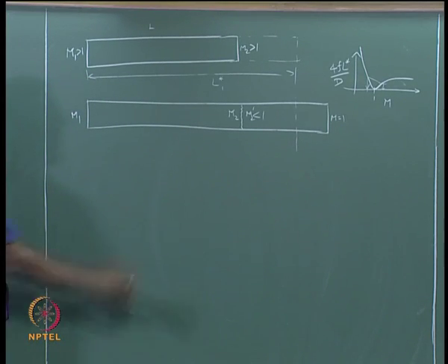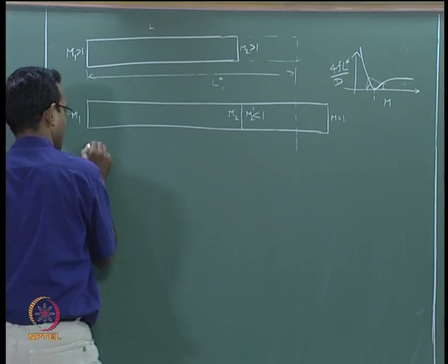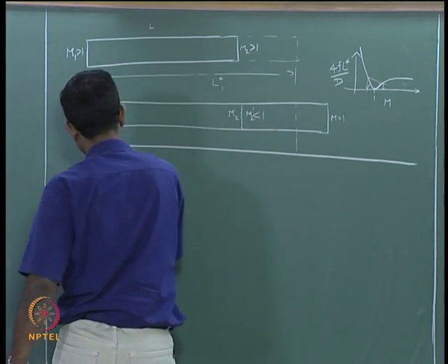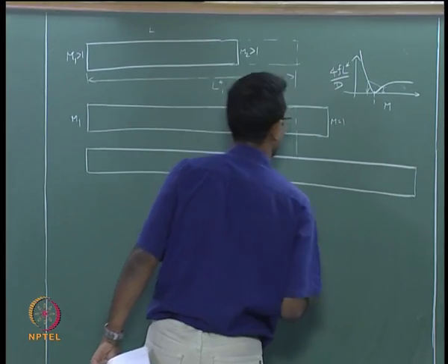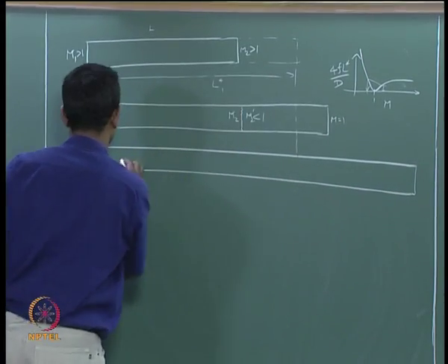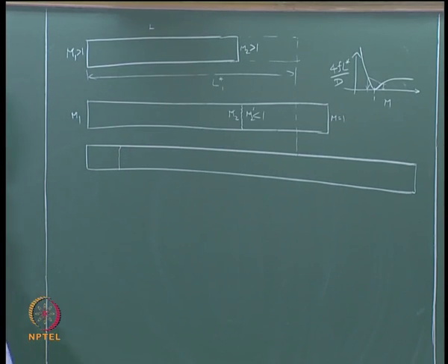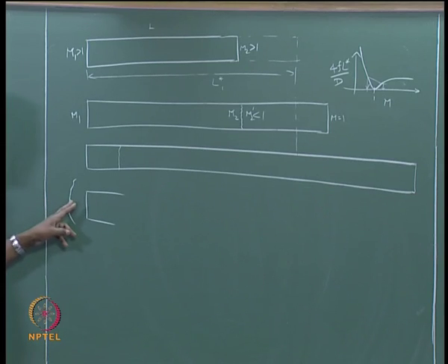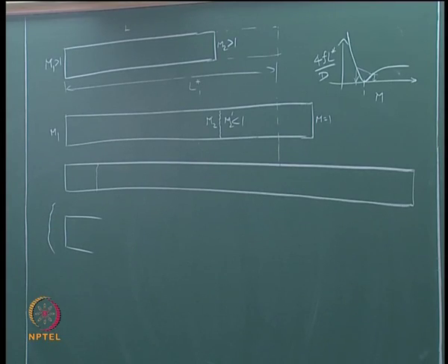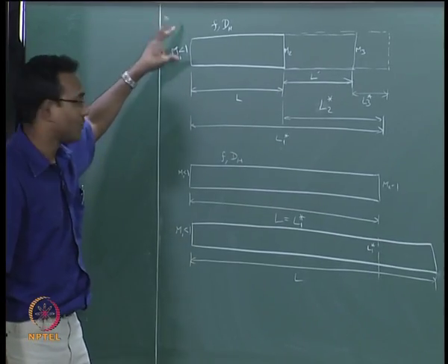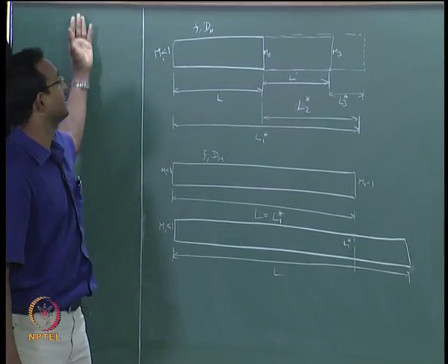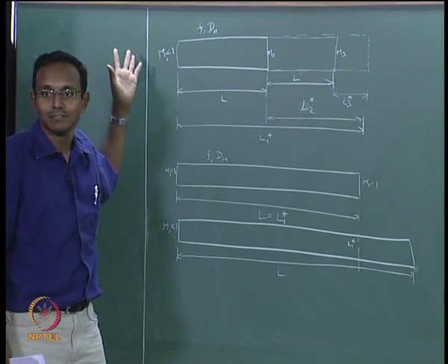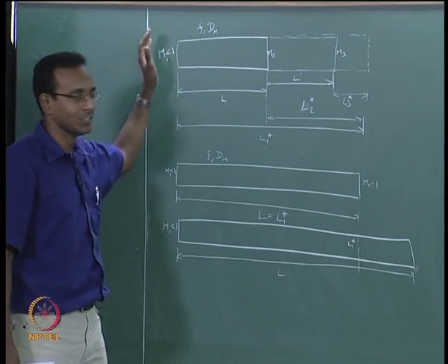Okay. If I keep on extending this length, then we will go to a situation where the shock goes more and more upstream. If I extend it any further, then the shock will go sit outside this duct. After that, if I look at what is the flow inside the duct, it is only subsonic flow. I will go back to the other board here and the problem just becomes this. Of course, there may be a shock sitting in front of it, and before that there could be a supersonic flow even here. I am not showing you that part here, that is all it should be.